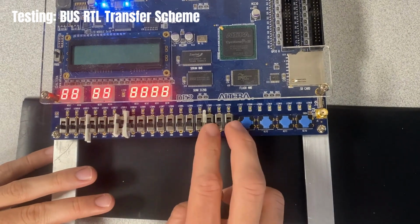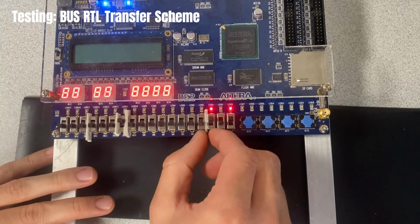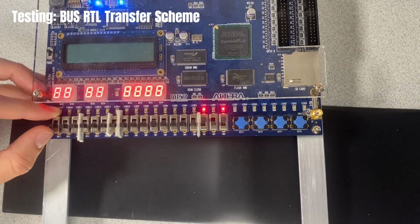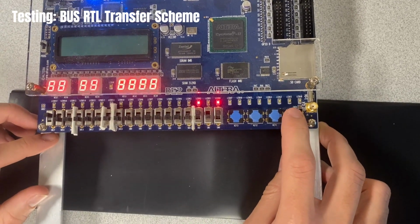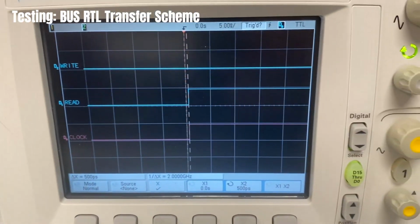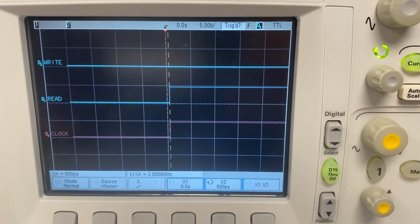So I'll set that high, set the input to 5, hit the clock, and that'll write it to register A. Now we can write the register A to the bus and take a look at the delay. There it is. And in this case, it didn't pick up a delay. Let me try it again.